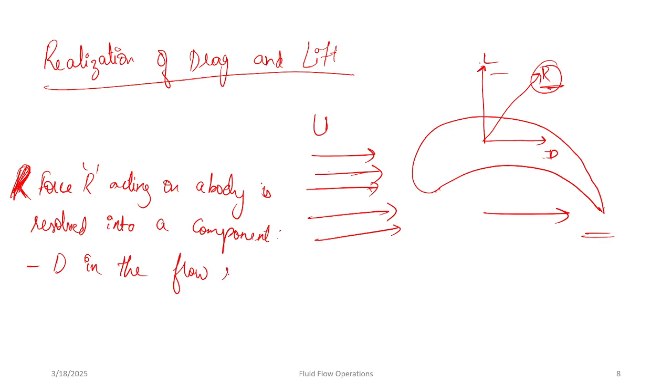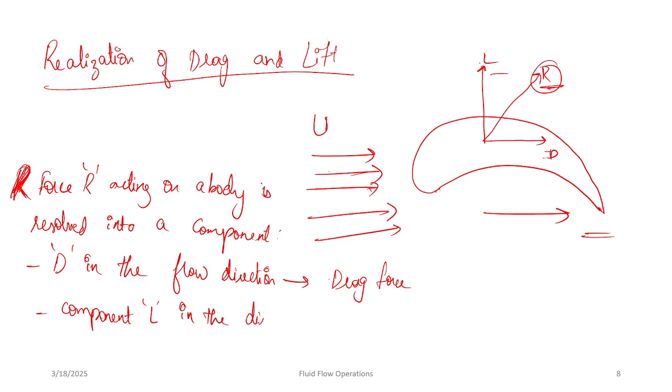So one is in the direction of flow. This is also called drag force, and the other one is component L in the direction normal to the flow, and this is referred to as lift force. Okay.